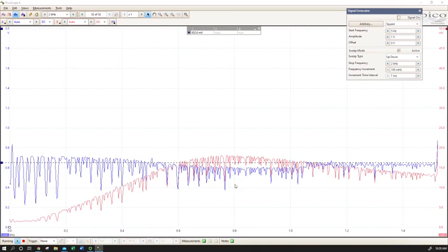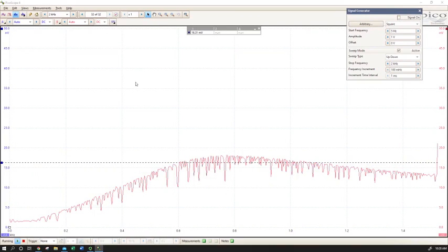Well, at this point we can probably stop. So I stopped the signal sweep, and we ended at a point where, for whatever reason, we're not on a scale. We're at a 50 millivolt scale for the whole circuit, so we can't see that. But we'll go ahead and use our x-axis ruler, and pick a frequency somewhere where we think the top of this peak is.